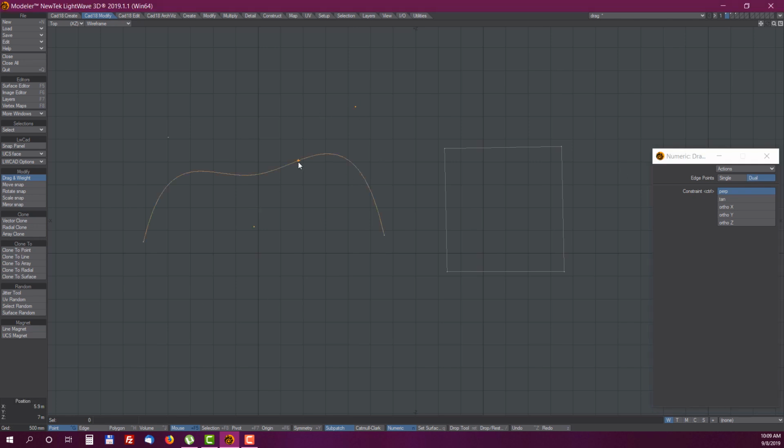So if I touch the NURBS surface here, I am dragging the nearest 2 control points. In case of the edge of, let's say, a NURBS rectangle or polygon or surface, then 2 points of the edge are modified. So this is the difference.